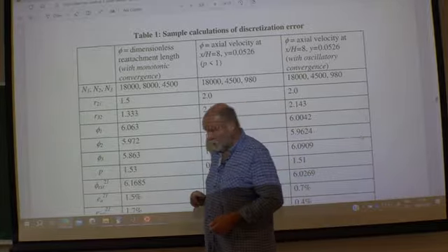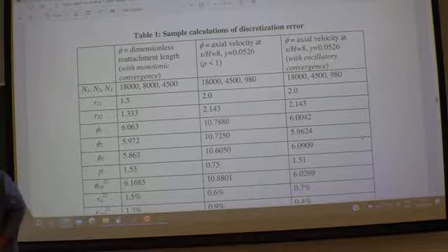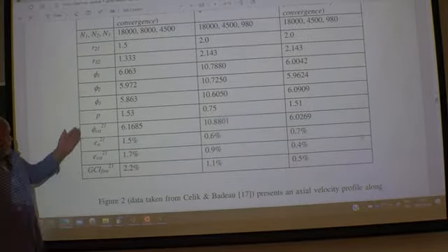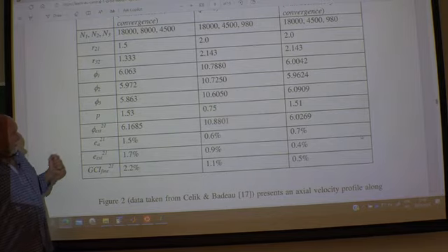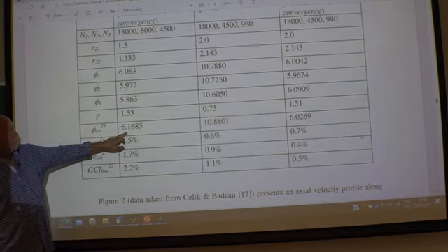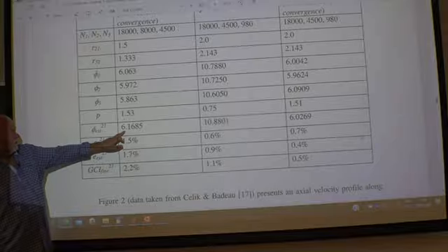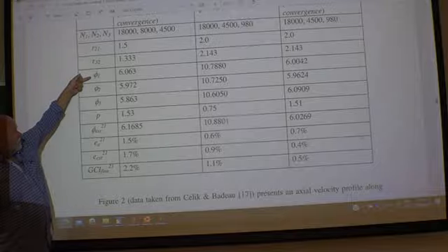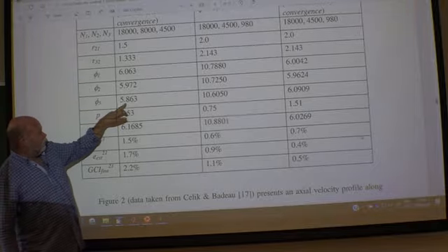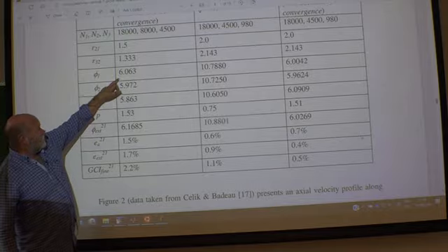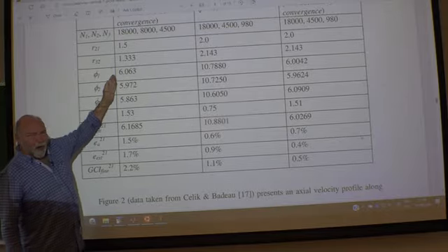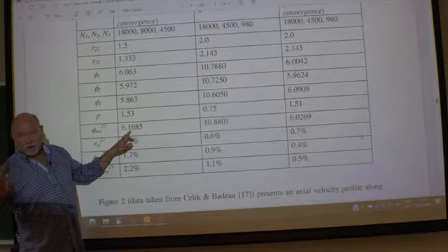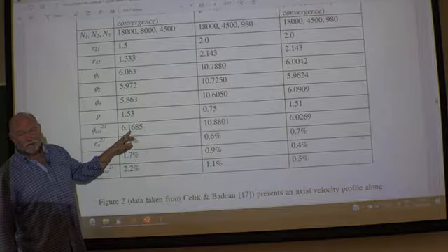Now, having found the p-value, then we can complete the diagram, finding the final, the extrapolated value. So here is tempting, isn't it? This is my finest mesh, coarsest mesh. So you see the value here tends towards this value. And now if you extrapolate, I get this value, forbidden. Not allowed to extrapolate, you never do that.